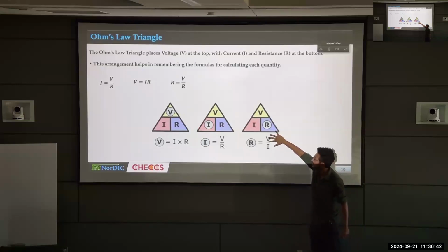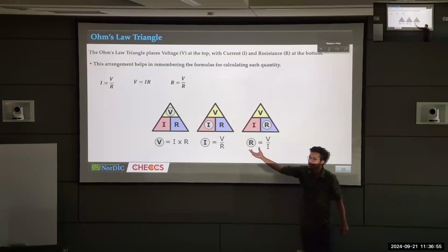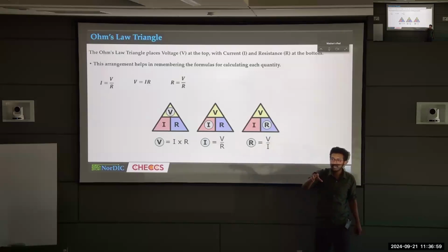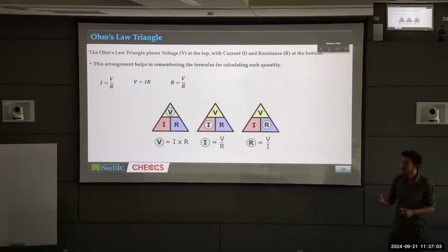If you connect three batteries, the current also increases 3 times. So you see that the division between the voltage and current remains the same because it depends on the material. See my point? So the resistance remains constant. That significant parameter defines the material: how much current will flow, how many free electrons there are inside.